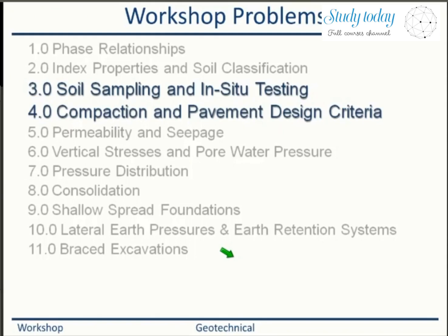Isn't the lack of basements best explained in the south by the high water table and shallow freeze depth? In the north, they installed basements because they have to go deep anyway to get below the freeze line. Oh yeah, that's pretty good, Matthew. I think you made a good point there.